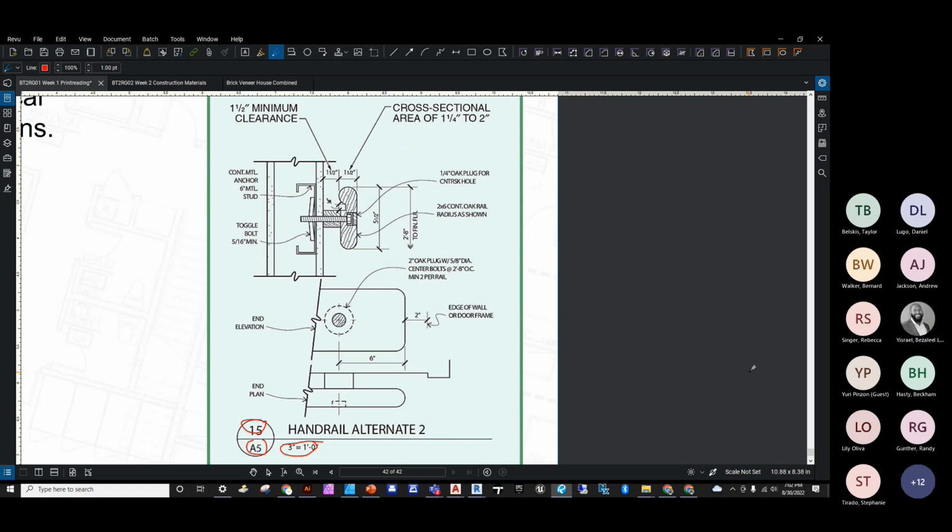That minimum clear stairway width not being less than 31.5 inches wide when your handrail is installed on each side, or 27 inches when handrails are installed on both sides of the stairway. So our handrails must be provided on at least one side of the stairway, a minimum of what? 34 inches and a maximum of 38 inches above those tread nosings.